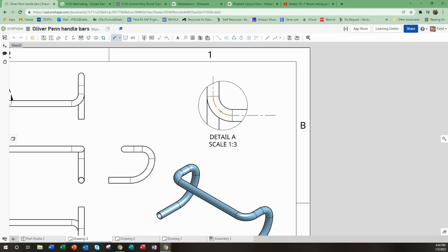So if I wanted to know the radius that we put, remember how we put in a 40 millimeter radius on that curve, if you drop dimension, you can change certain things about it. We're going to really start to explore this most important of the elements. This one just tells you is it a radius or a diameter. And I could change that to diameter. Here's the actual measurement value, and here's the tolerance.